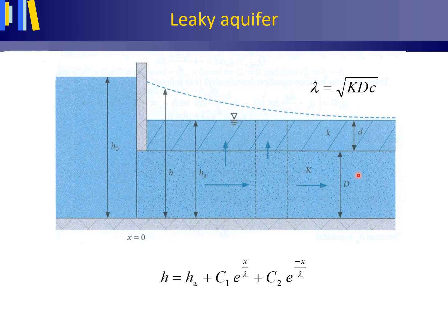Water is pumped from the polder and the hydraulic head or water table in the leaky confining layer is, to keep our feet dry, artificially maintained at the level HA in meter. In reality, this HA would lie slightly below the land surface, but here, simply for ease of calculation, HA has been set at the land surface. As the reference level, a hydraulic head of 0, we will use the top of the underlying impermeable base.